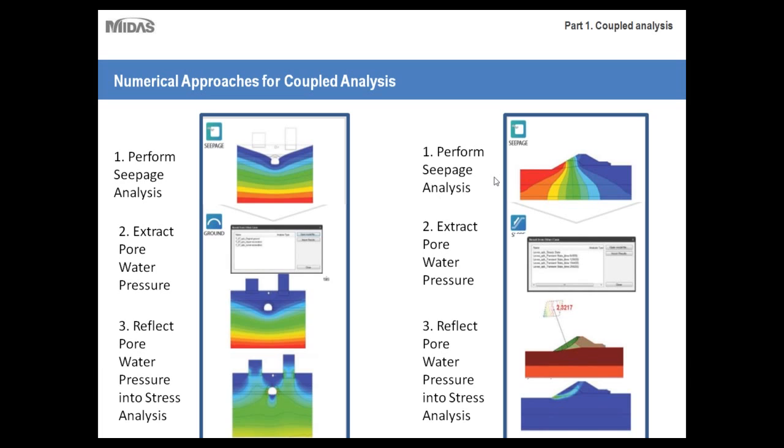So here we have another similar embankment type problem. Because there's water on this side of the embankment, the head is maximum at this side, and then it's minimum at this side, and you'll experience a significant amount of seepage on this side of the embankment. So what you would do, using the program, is run your seepage analysis, get your pore water pressure loads, and then import them directly into your slope stability analysis. So you wouldn't even have to change your model file.